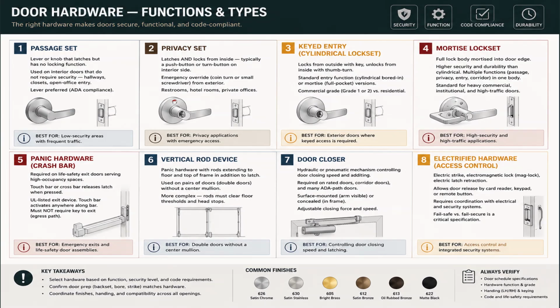And, this is critical, it must not require a key to exit. The egress path always has to open from the inside with a simple push. Best for emergency exits and life safety door assemblies. A vertical rod device is panic hardware with rods extending to the floor and top of the frame in addition